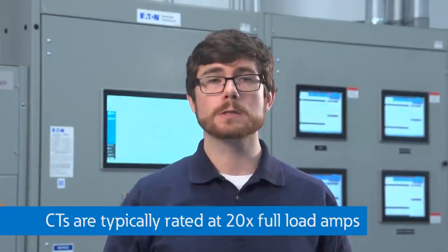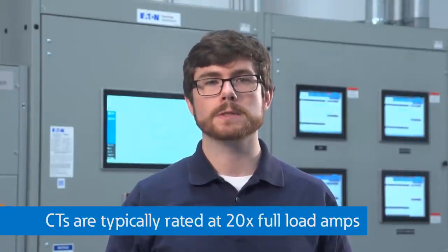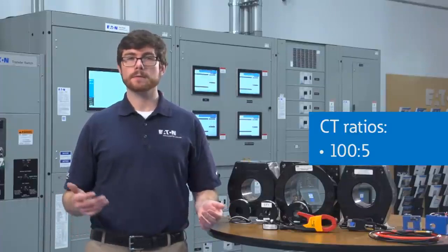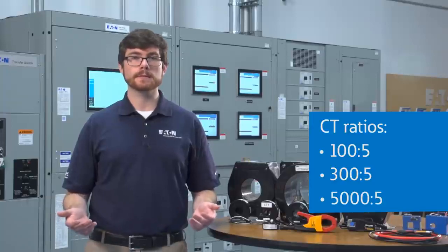For all protection applications, CTs must be rated to accurately measure the high currents that are possible during fault conditions, usually 20 times full load amps, so that the breakers can trip in the proper sequence without saturating, which yields an incorrect result. CTs come in many different ratios, such as 100 to 5, 300 to 5, 5,000 to 5,